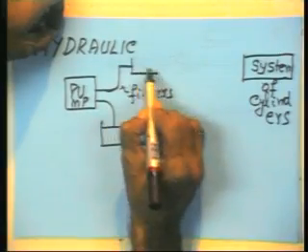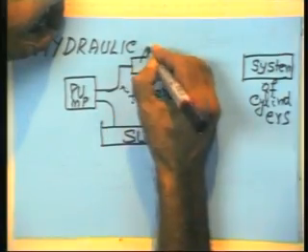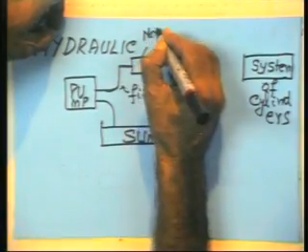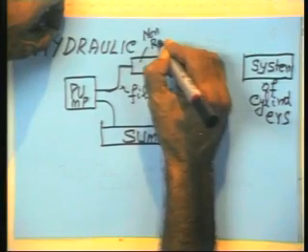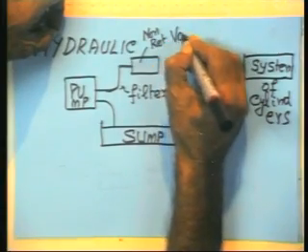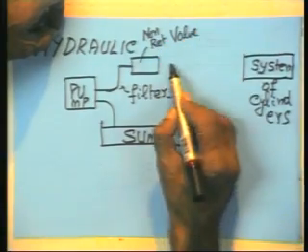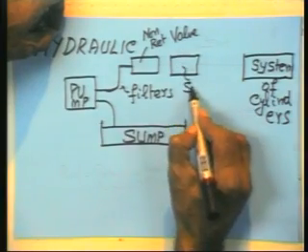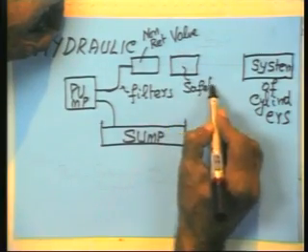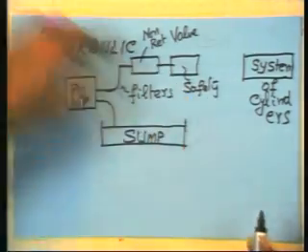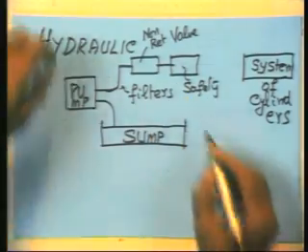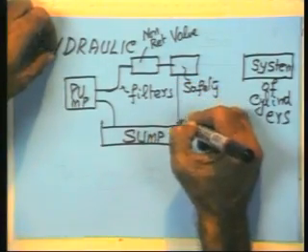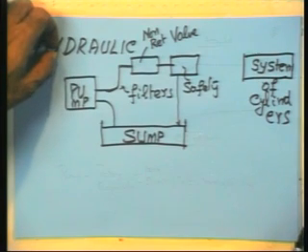Then there is what is known as a non-return valve. This is a typical non-return valve. Then there is a pressure release valve, a safety valve. Sometimes for some reason if the pressure in the system goes up, the valve will release the oil, usually back to the sump. Remember that. You can't throw the oil all over the shop floor. It goes back to the sump.